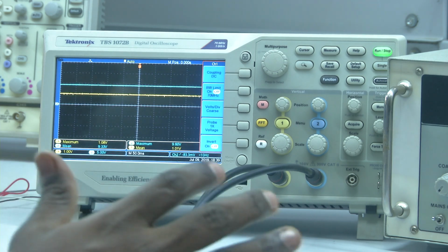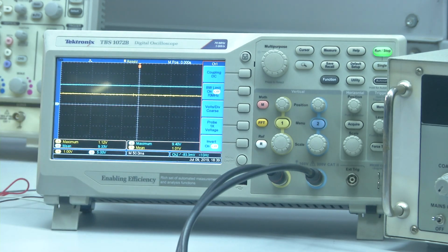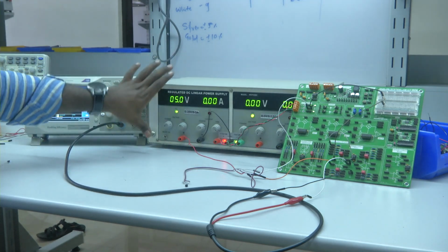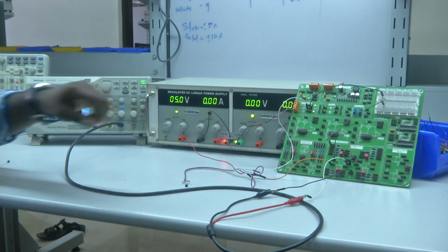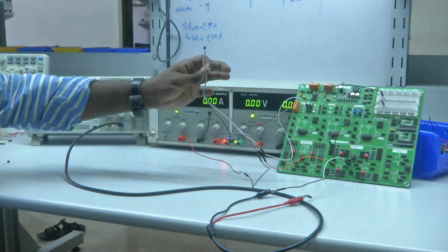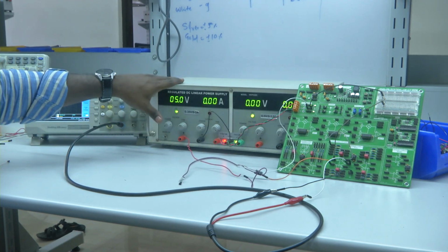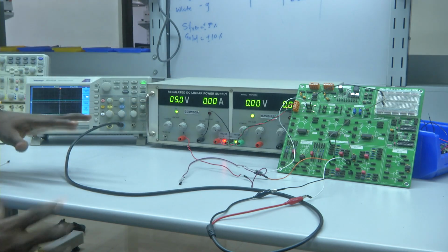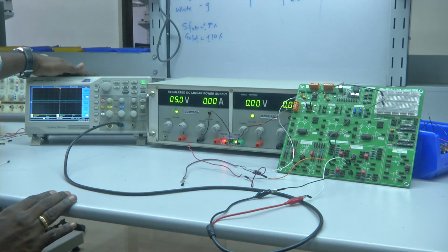Now, what we do is remove the connections on the input side and interface it to the LM35 temperature sensor. We will perform the same experiment as we saw previously. If you see the connections, I have replaced the input from the power supply: the output of the temperature sensor is now connected to the non-inverting terminal. Since LM35 requires a power supply voltage, 5 volts has been provided from the first channel of the power supply. The output from the complete stage is connected to the second channel of the CRO.